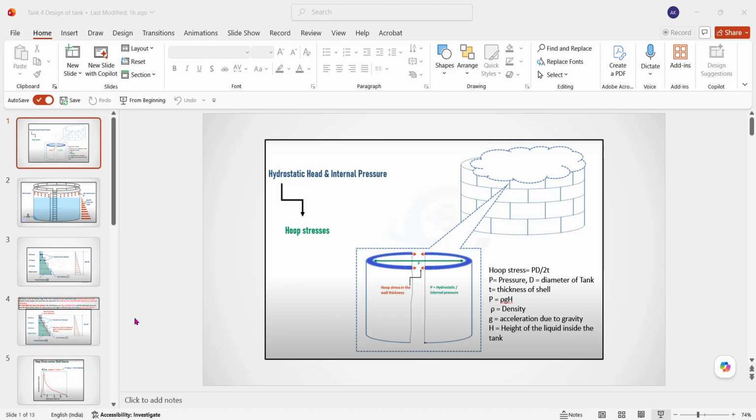it is more conservative than the variable method. Here the thickness you will get will be more than the variable method. Then the calculation of thickness you get from using the variable method. The 1 foot method will give you the more conservative result, means your thickness will be more, and tank diameter is often limited by the thickness criteria. And next is your variable point method.